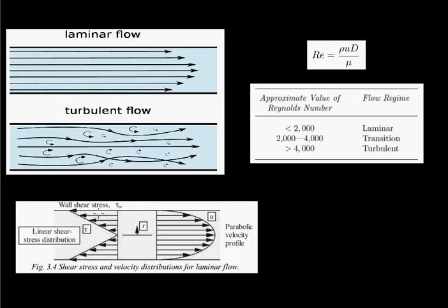And then that fluid that's slowed down by the wall is going to slow down the fluid moving next to it, and that fluid is going to slow down the fluid moving slightly below it in this picture, and so on. So you have this flux of momentum in the y direction, or in the radial direction in this case. That's the way to think about shear stress.